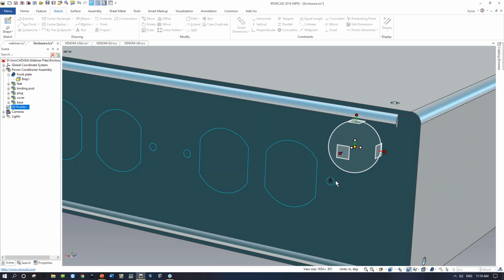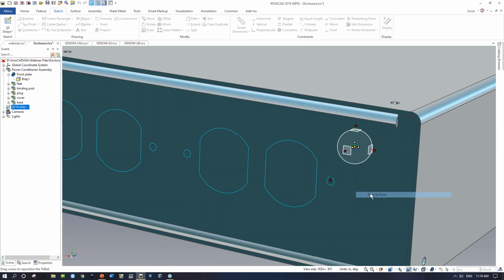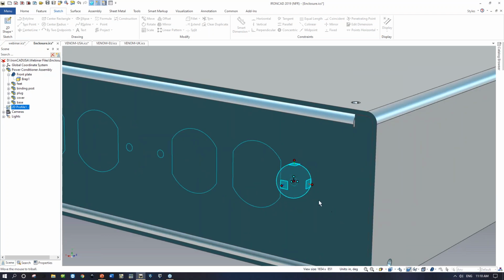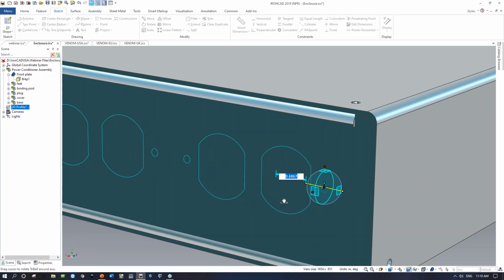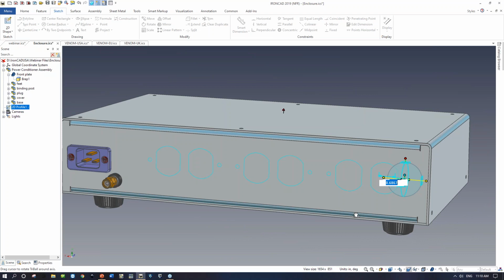This is not even a circle, it's a polyline. So what I need to do is say, instead of at the center, because there isn't one, I want you to measure for me and put it right at the location there. So I've actually placed it. Why? Well, that now allows me to move this exactly into position on this front face, and I can locate from a line, I can locate at any point.